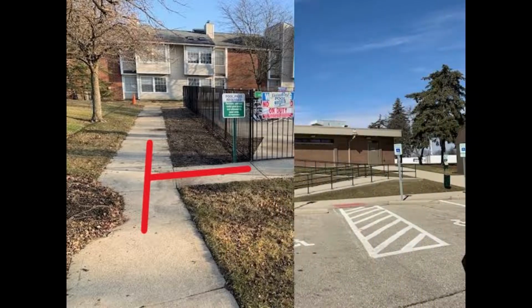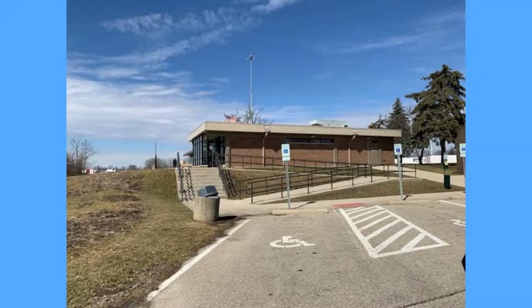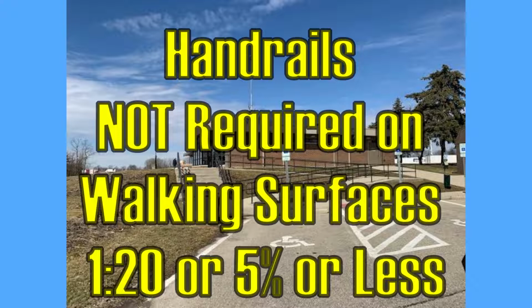Handrails are not required on walking surfaces less than 1 in 20. However, if they are provided, they must comply with Section 505.